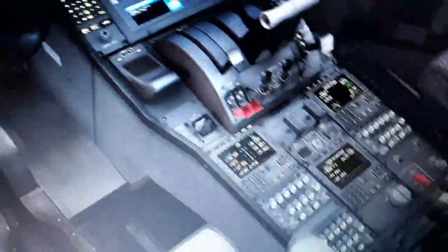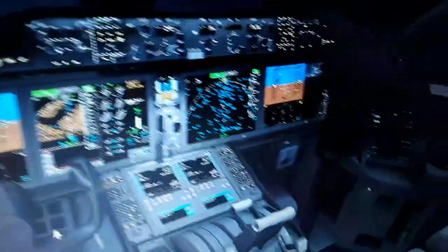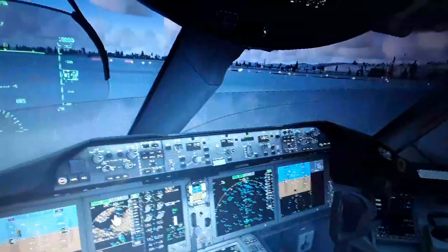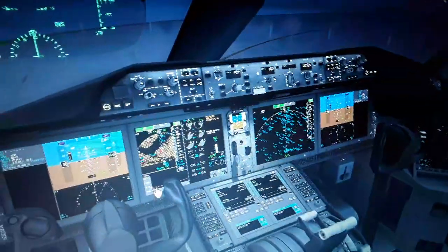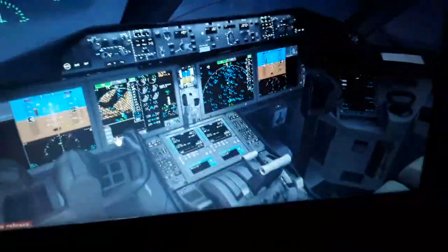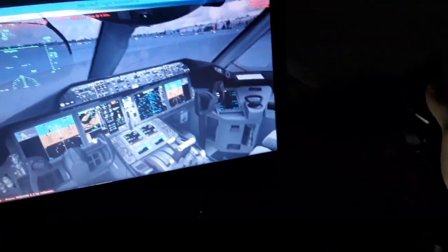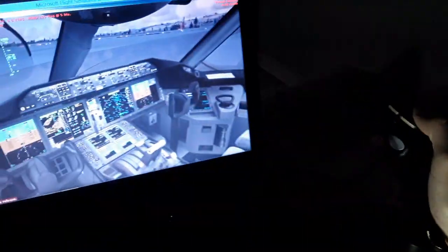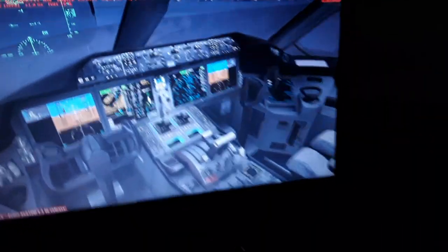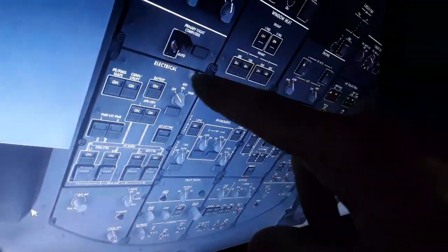This is another separate radio communication panel here. So we're going to lose the auto trim, the automatic trimming of the aircraft. So you're going to have to fly the aircraft manually like this, and use the manual trim switch or the alternate trim switch here. You can see it's a fly-by-wire aircraft. It has its flight control computers. So the Boeing 787 has flight control computers, like the Airbus has flight control computers that control the aircraft movement, flight controls in the air.